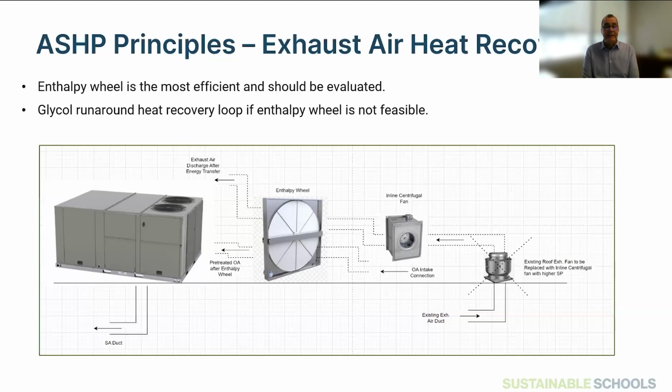We have schools that were built in the 1980s that still utilize the same technology. A lot of our similar design elementary schools are fitted with 19 heat pumps. Some of them do a couple of rooms, some are dedicated to one classroom. We run the compressors on those down to -5. Most of them are controlled by building automation, and then we lock out the compressor below -5, and we switch over to electric duct heaters.